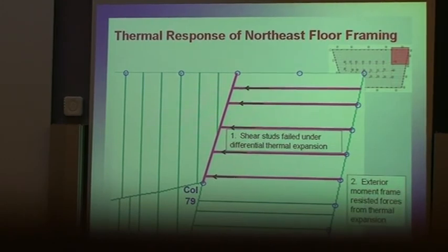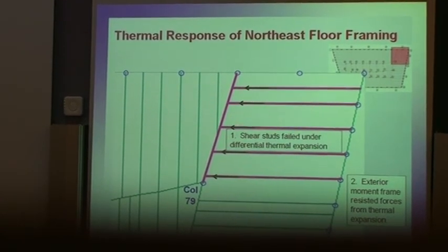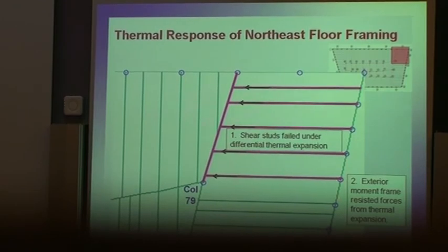And that led to the thermal expansion of these beams freely. You can see here, the exterior wall is very rigid because the span between each 2 columns is small. However, this side is more flexible, especially as there are no beams resisting the thermal expansion.